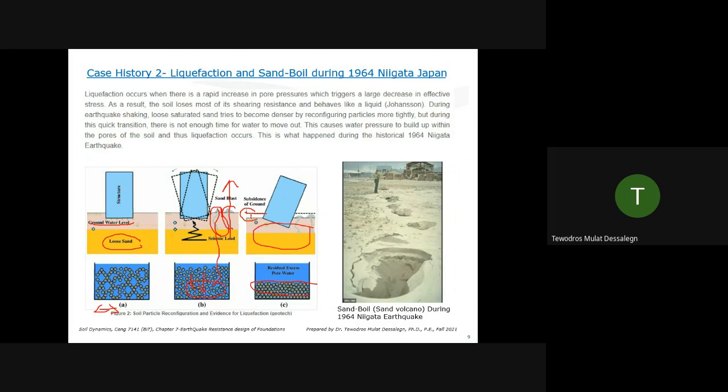We are having some settlement. The whole ground is going down. You see it, the initial and the final one, and some instability in between. It's a complex dynamic phenomenon. But the major takeaway is high water pressure is created in that loose sand deposit, and that high water pressure escaped through, we call it sand boil, and then it causes semi-liquid sand, and now buildings are unstable.